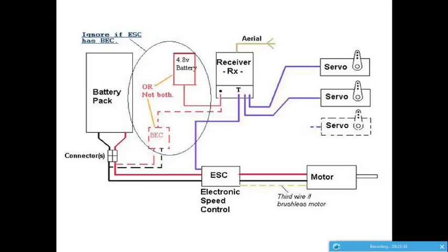So you need to connect the corresponding servos of the control surface to the corresponding channels properly, and also before flying the model you need to check all the servos and the control surfaces by moving them using the transmitter.